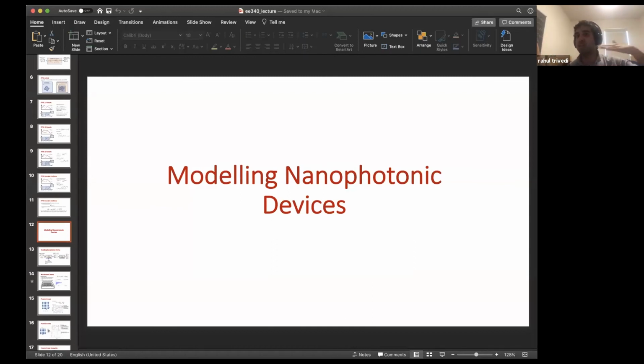With PMLs, you don't need it to be a perfect plane wave or a spherical wave. But if you have evanescent waves that are interacting with PMLs, they'll actually radiate through. So even with PMLs, you have to be far enough so the evanescent waves in the device have decayed, and all that you're hitting it with are plane waves that are not very oblique, right? So if you're simulating a device that has very strong evanescent field, you might have to put your PMLs somewhat farther away from the device. It does depend on the physics of the device you're working with. For most optical waveguide-based simulations, for most optical devices, one wavelength to two wavelengths works well in practice.